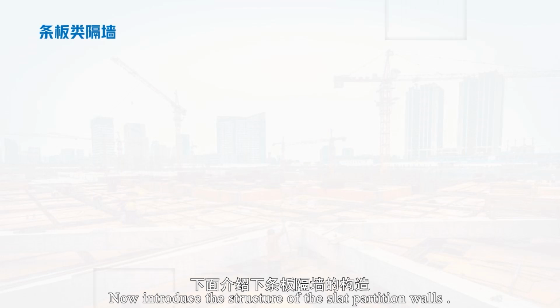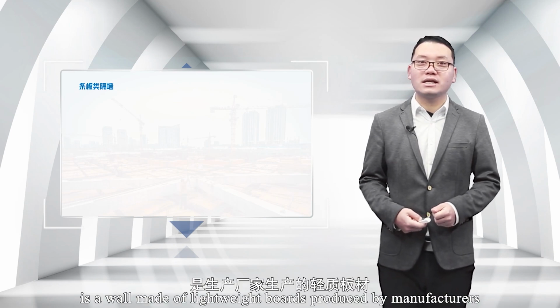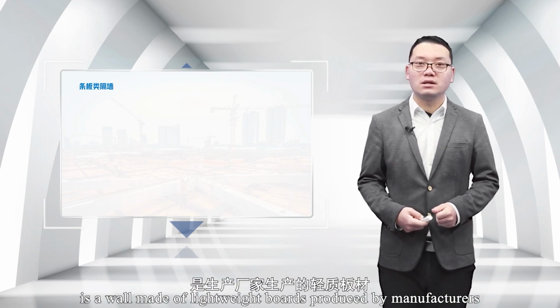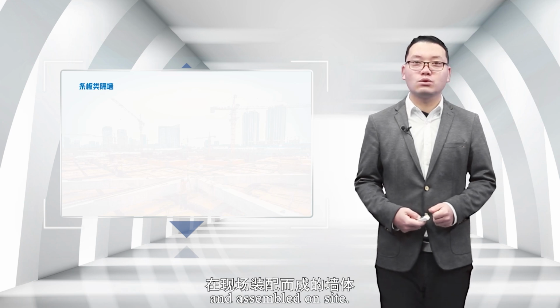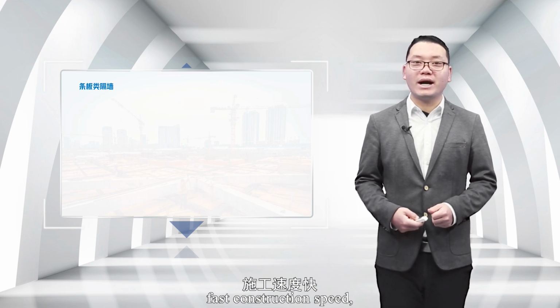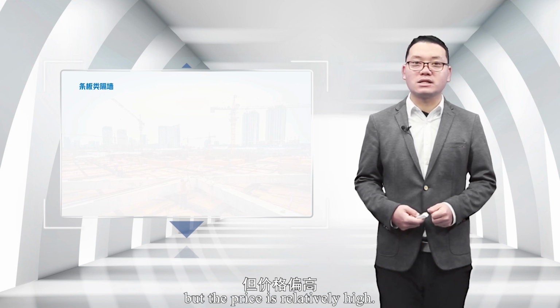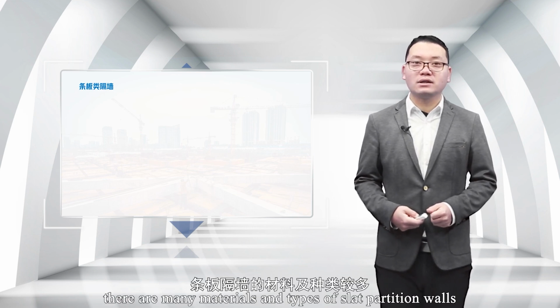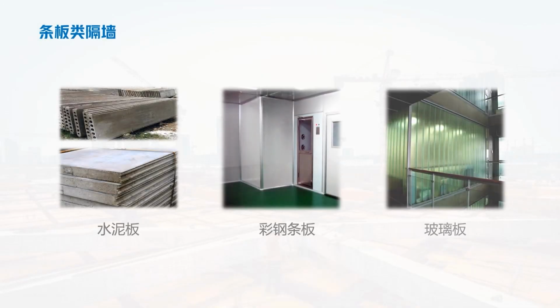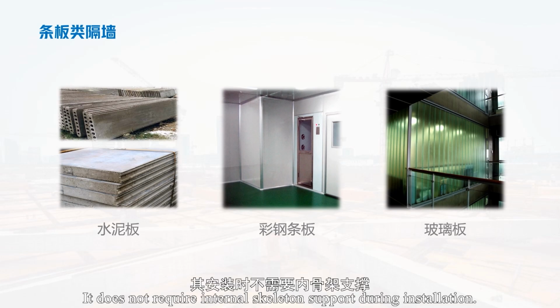Now we introduce the structure of the slab partition walls. Slab partition wall is a wall made of lightweight boards produced by manufacturers and assembled on site. This type of partition wall has good assembly, fast construction speed, and good fire resistance, but the price is relatively high. Currently, there are many materials and types of slab partition walls, such as plasterboard, cement glass fiber hollow strip board, etc. It does not require internal skeleton support during installation.